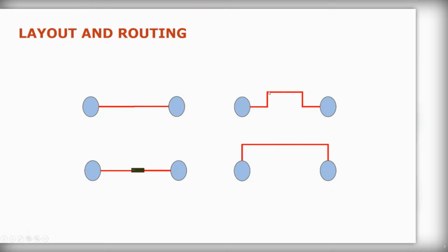Well, you can put an expansion loop like this. So that gives a zigzag into the layout. Now what can happen is this elbow can slide inwards, this one can slide inwards, and those elbows are pushed outwards. And those legs here, the absorbing legs, allow for that motion to happen like a little harmonica, like a spring.